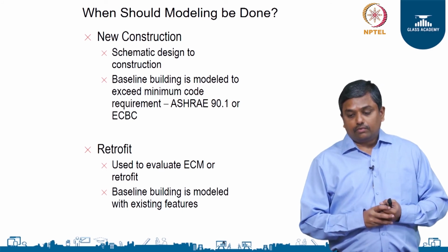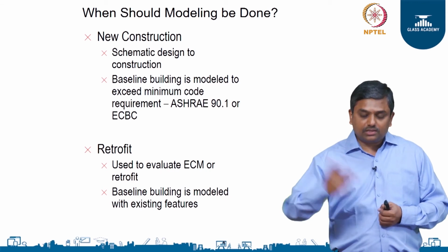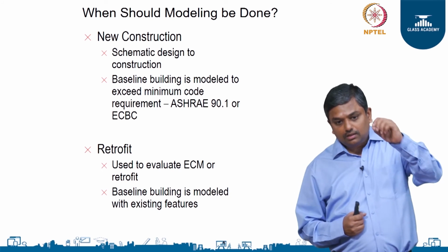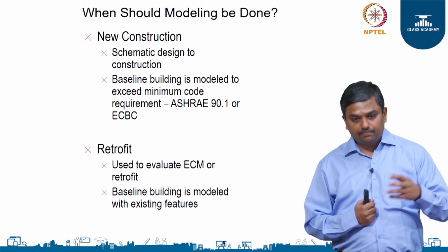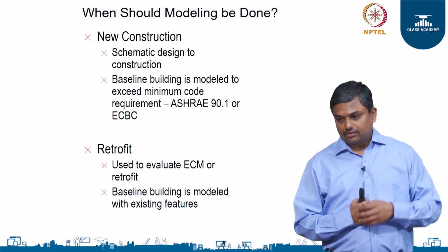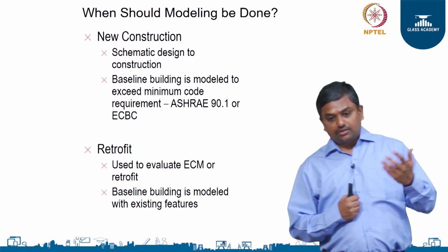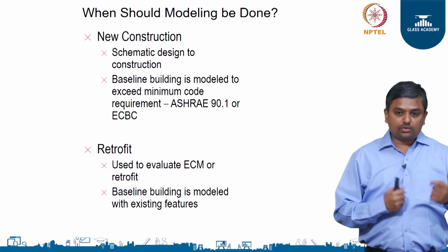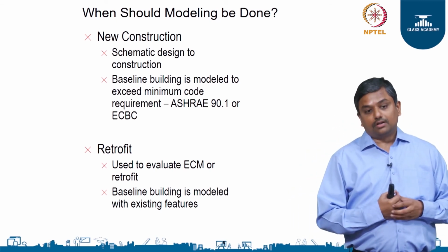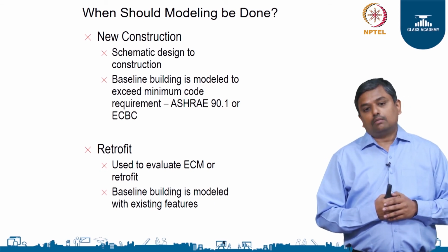But where they become extremely important is to analyze the incremental benefits of design alternatives that you want to propose. So, what if I change a certain material in a facade to something else, or if I add a particular device or a shading device, for example. So, how your building is going to change incrementally, whether it is going to be worse or better in terms of energy performance. So, these incremental benefits can be programmed fairly accurately using modeling tools. So, that makes it very effective in making prudent design decisions.